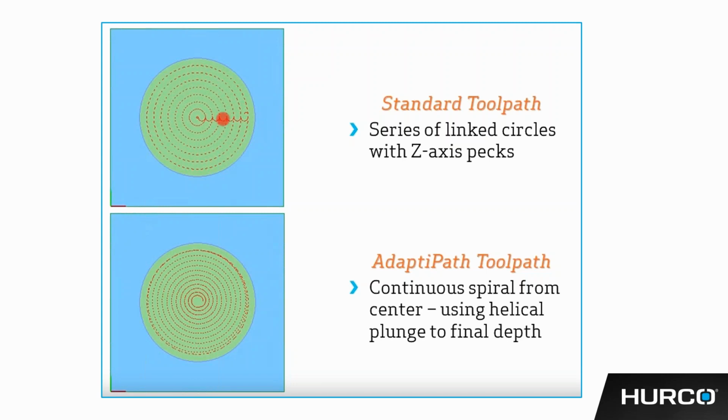Well, what we're trying to eliminate here is that step over move. Every time you get to that start point and it comes time to transition over to the next cut, your tool is engaging a lot of material, more material than in your standard routine there. So typically you have to base all your feeds and speeds, your step over, depth of cut, that's all typically based off of that little transition move, because that's where you're going to be engaging the most material.